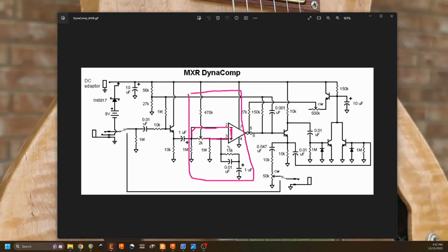An op-amp is a device that is trying to always keep the voltage the same at the two input terminals, but the operational transconductance amplifier is actually taking the difference between these two terminals and amplifying that. And so in order to make sure that the device is giving you the best amplification swing with minimum noise requires that you carefully balance the input to each side.